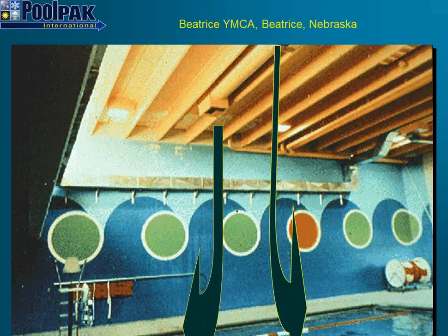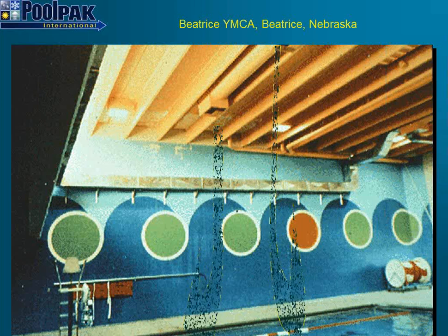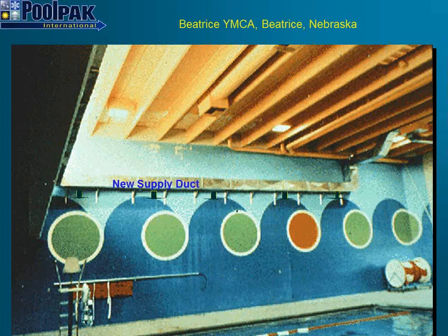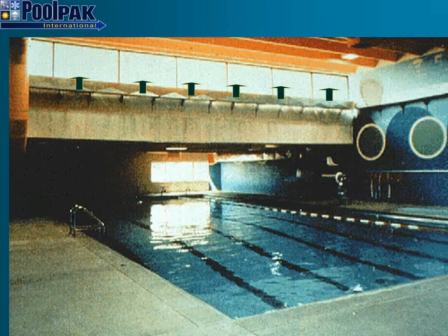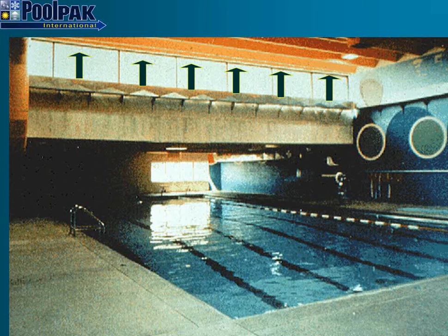What we want to do is wash the walls with the airstream, keep condensation from forming, and keep the air moving around so chloramines, if occurring, do not settle on the walls or condense on the walls or on the deck. We also need to treat the windows with a good stream of dehumidified air. So place your ductwork so we wash the windows so condensation does not form there.